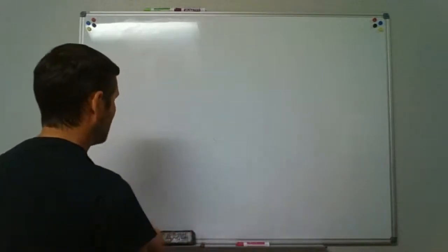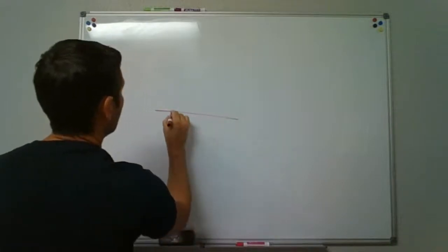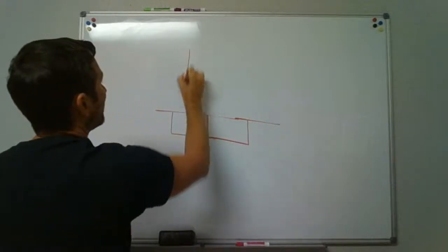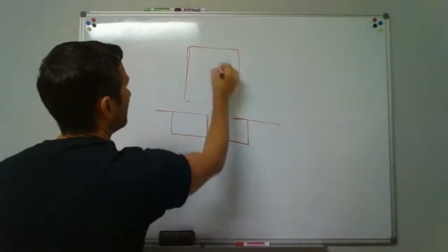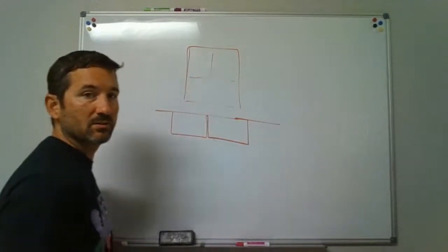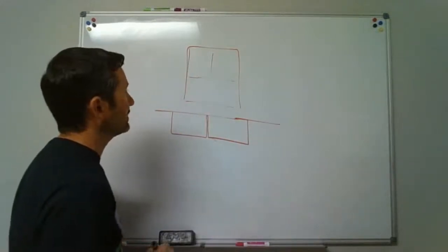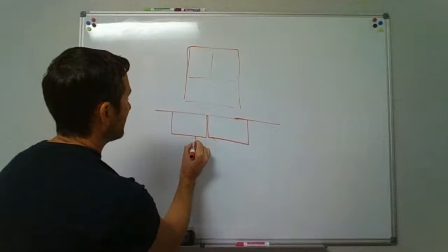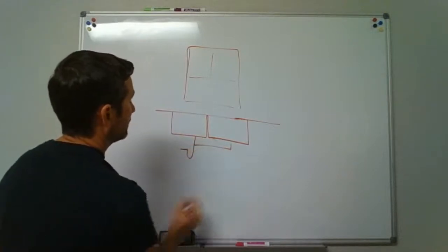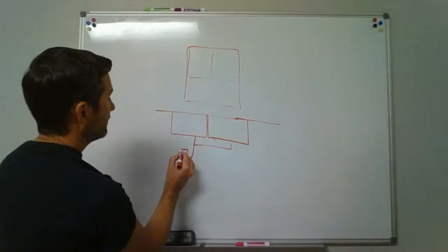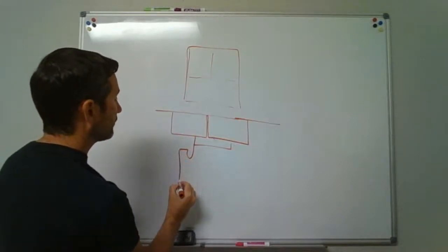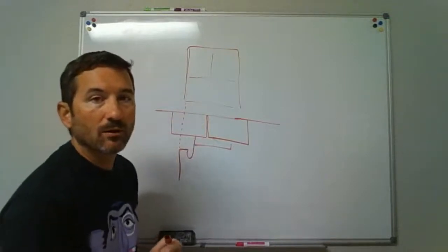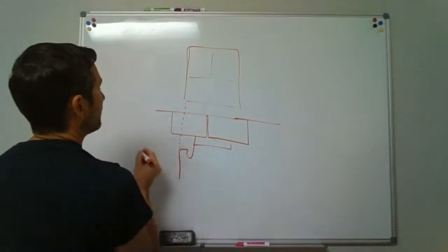So another case, kitchen sinks are often located with maybe a nice window above your sink. Okay, so you can wash your dishes, look at the kids, see the kids play in the yard or whatever. So if we had a trap come down out of this one and it went back into the wall, but we said that back in the wall, that drain's going to go down through the floor. To get it to go down, we got to go up with a vent. And then you say, oh no, our vent's going to be in that window. So we got to get out of the way of the window.